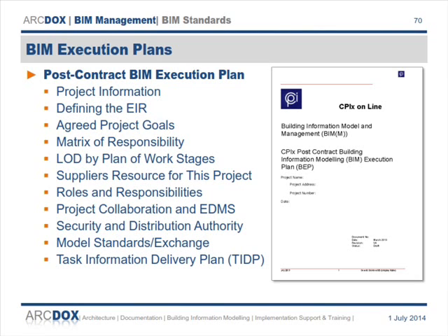Okay, so the designer's model is there as a background, as a reference document. Yeah. What the contractor has to do is bring together the steel fabricator's model, the glazing contractor's model, the precast model, into a federated construction model over the course of construction. And it does involve modelling things that companies wouldn't normally have done.